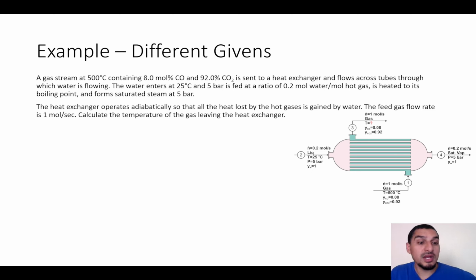And the reason is we already know the details of water, the information about water. You can go to the steam table and extract the data. And there's a point that we discussed at the beginning of this chapter: in the cases that we dealt with the steam table, we didn't even worry about the changes that happen. We only needed to know the conditions at the feed and the conditions at the product, and this is all we need to get the two enthalpies.